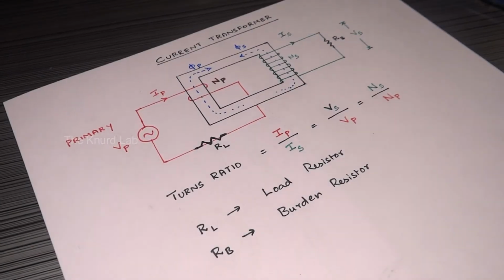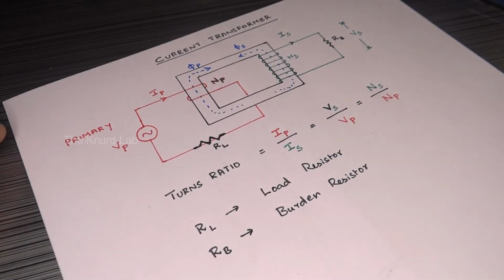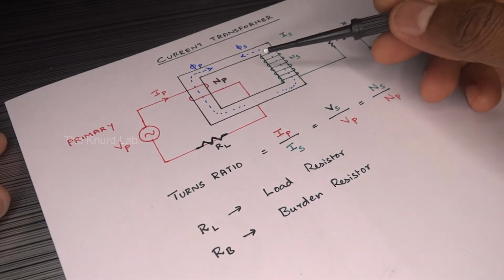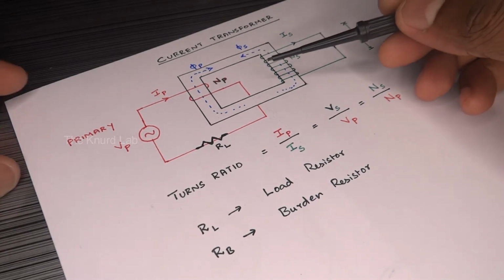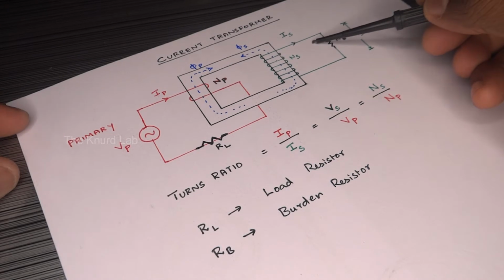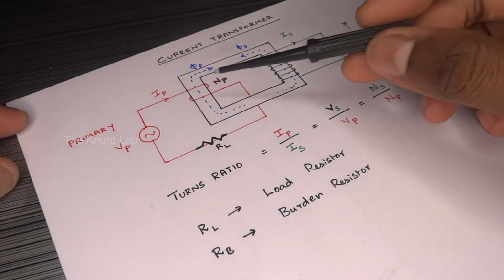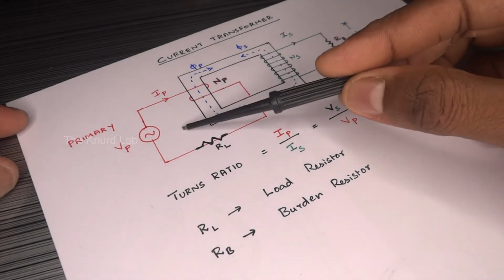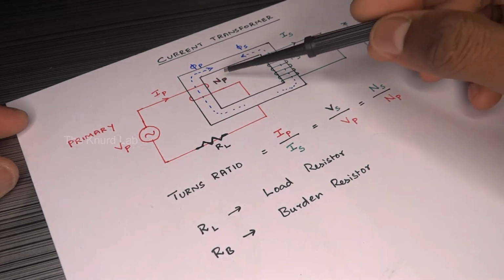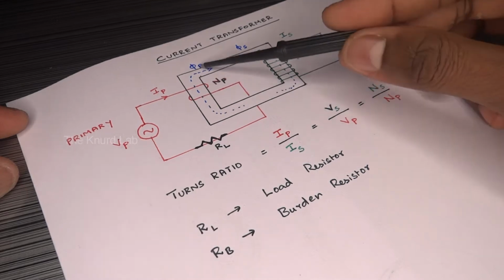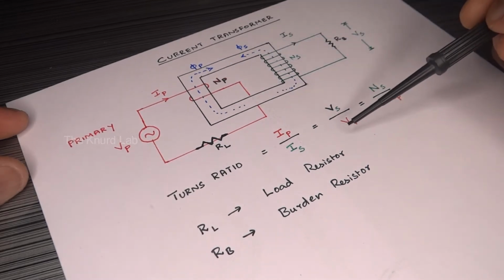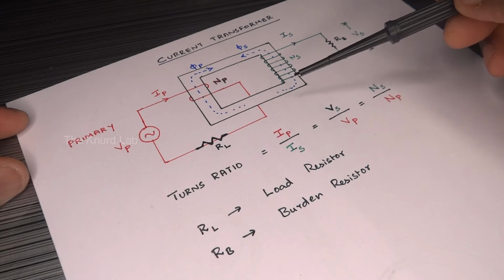Unlike power transformers which are used in power distribution systems, a current transformer is used as a sensor or an instrument to safely step down and measure large currents in a non-invasive manner. To achieve this, the primary side usually consists of one turn and the secondary side a large number of turns. The secondary is also short-circuited through a burden resistor. This way, the secondary current is always proportional to the primary current, which is determined by the turns ratio.